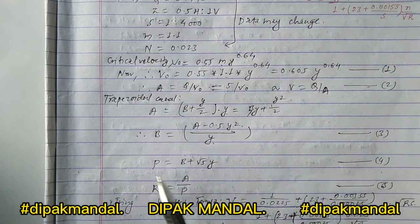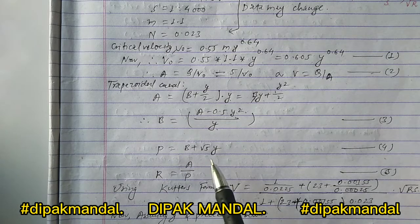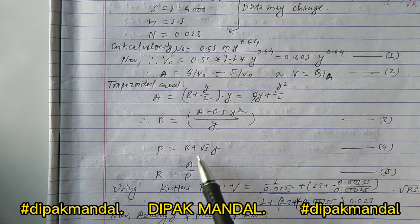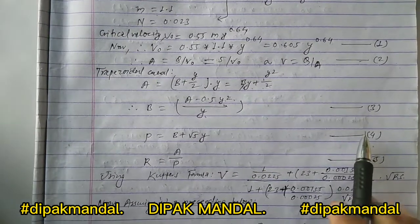Now we have to calculate the value of P, the perimeter. As you know, the perimeter of a trapezoidal canal is P equal to b plus root 5 y. Let's assume this is equation number 4.